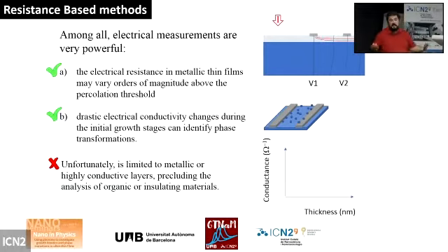In order to do that kind of measurement, we only need a power bank and a source measure unit, and we can easily monitor at least the threshold when the impingement between islands arrives, and we can detect that point. This is for sure interesting in order to identify that point. We can also measure phase transitions through the electrical resistivity, but this is limited to materials that are highly conductive, because we need the electrons to percolate through the islands.